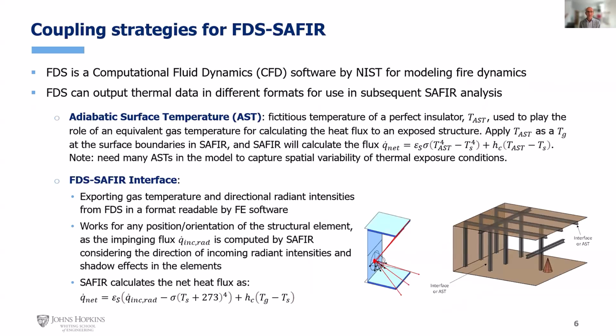Specifically with the Fire Dynamics Simulator developed by NIST, there are two main methods to interface the outputs of the FDS calculation with the subsequent thermal mechanical analysis in SAFIR. We've discussed some of these today. So the first method is through the use of an adiabatic surface temperature.